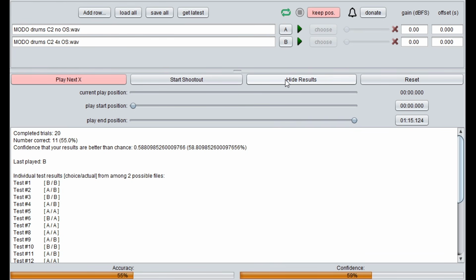Note that it's absolutely critical the two files are properly level matched for a test like this. Even 1/10 of a dB difference is enough to make one file sound better than the other. Note, however, that the ABX test doesn't require any subjective judgments about which sounds better. This is not a subjective which file sounds better test. It's a scientific, objective test of can you actually hear the difference? And logically, it should be the next step after a null test confirms that a difference genuinely exists. The follow-up question is surely, okay then, but does it matter?